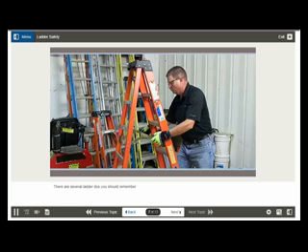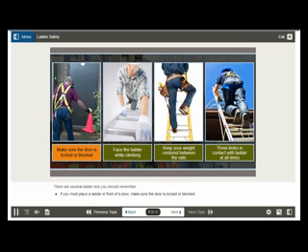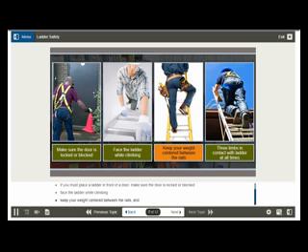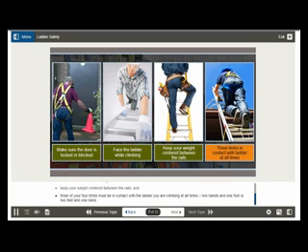There are several ladder do's you should remember. If you must place a ladder in front of a door, make sure the door is locked or blocked. Face the ladder while climbing. Keep your weight centered between the rails, and 3 of your 4 limbs must be in contact with the ladder at all times you are climbing: 2 hands and 1 foot, or 2 feet and 1 hand.